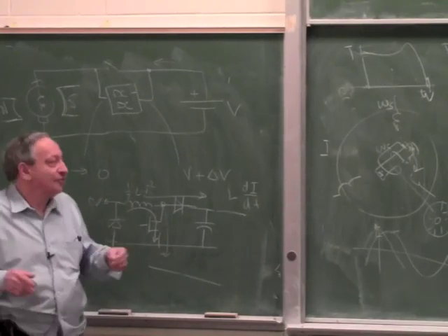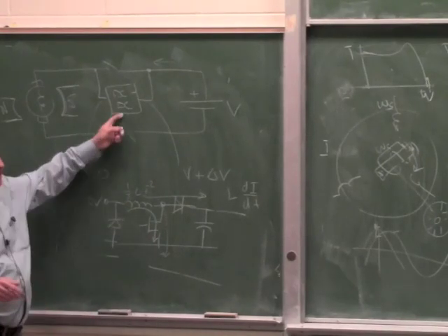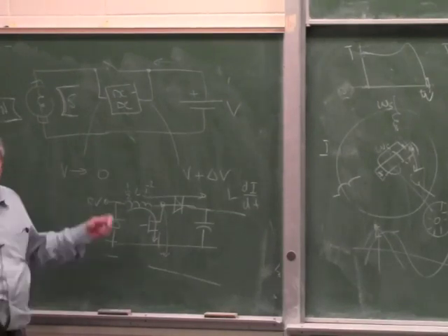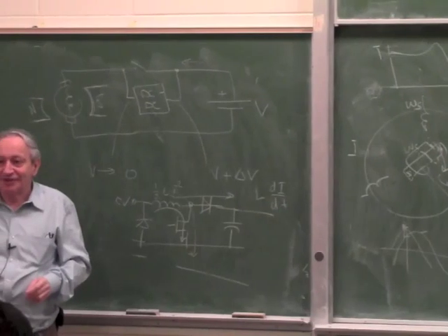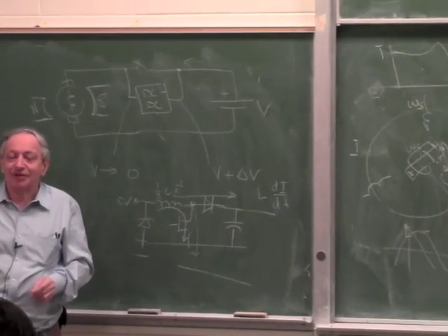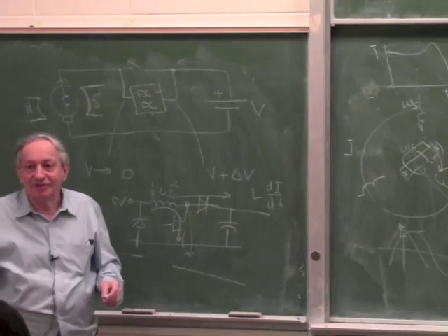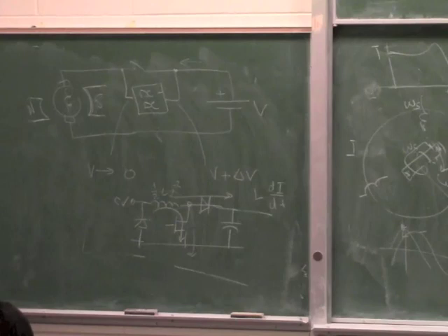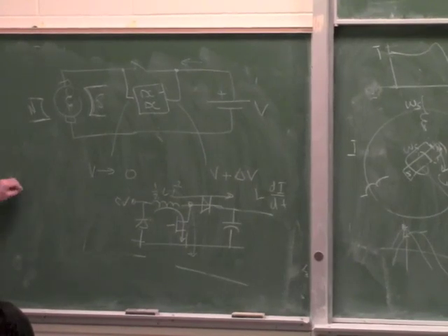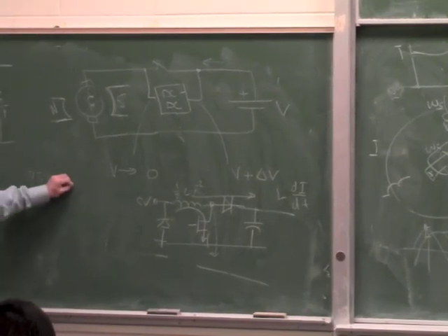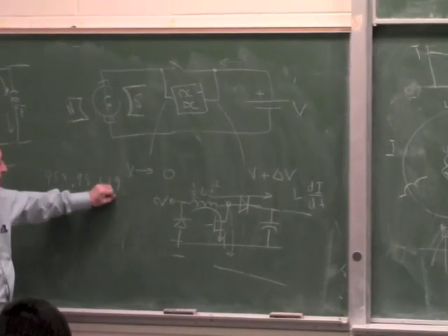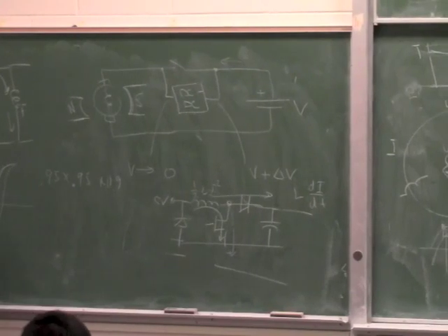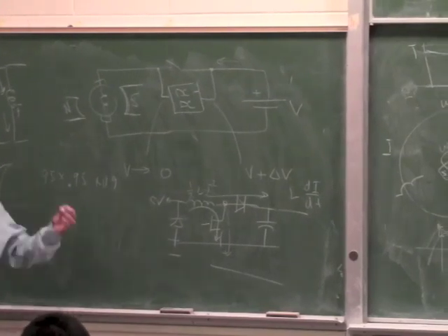Because if you really do a very good job with a DC to DC converter, it is like 95% efficient. A generator is like 95% efficient. And the battery is 90% efficient. So if you really do the math, even for an electric bike which is well designed, you get 0.95 times 0.95 times 0.9, which is the battery. So you get overall maybe 80%, but it's not bad at all. So most of the energy does recover to the battery.